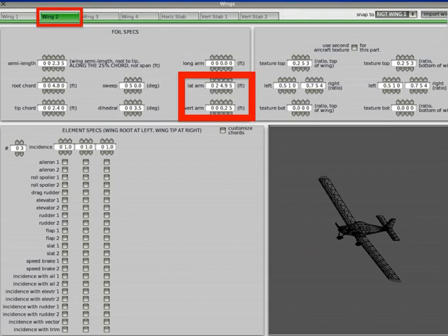All right. So with that in mind, you're going to have the kids put the wingtip in there. They're going to fly. They're going to take off. They're going to find out that their takeoff distance decreases by increasing the aspect ratio. Long, thin wings like this take right off. The plane will jump right off. And that's what's so exciting about using PlaneMaker. It's going to give you what really would happen.